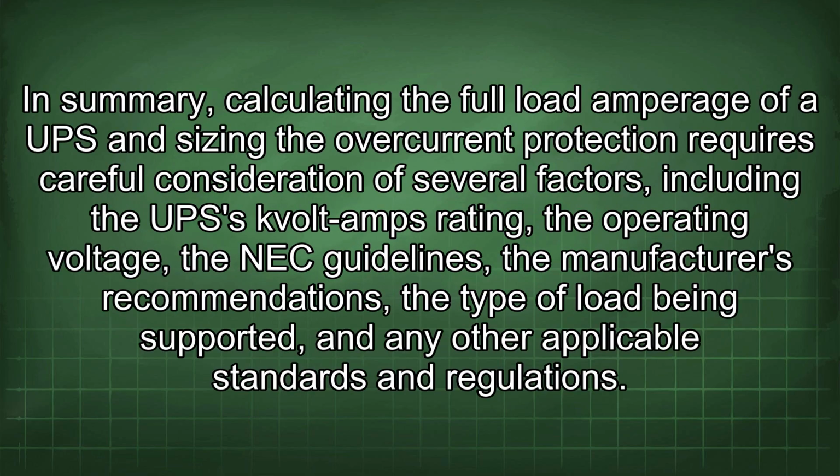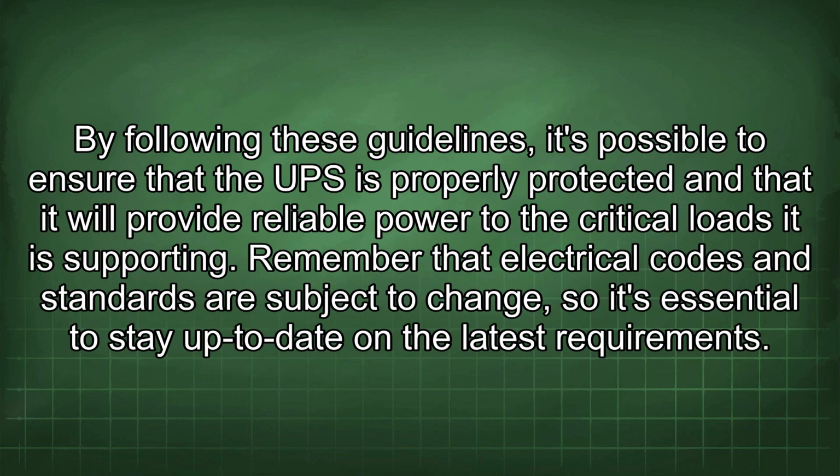In summary, calculating the full load amperage of a UPS and sizing the overcurrent protection requires careful consideration of several factors, including the UPS kilovolt-amps rating, the operating voltage, the NEC guidelines, the manufacturer's recommendations, the type of load being supported, and any other applicable standards and regulations. By following these guidelines, it's possible to ensure that the UPS is properly protected and that it will provide reliable power to the critical loads it is supporting.